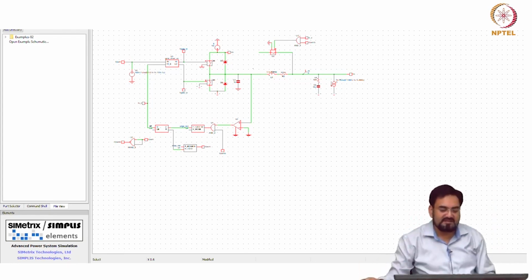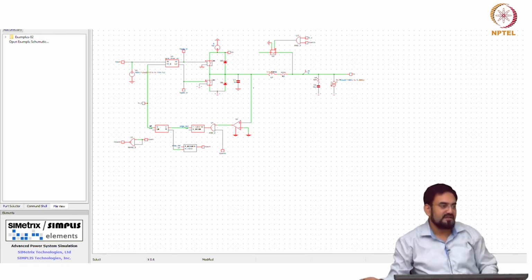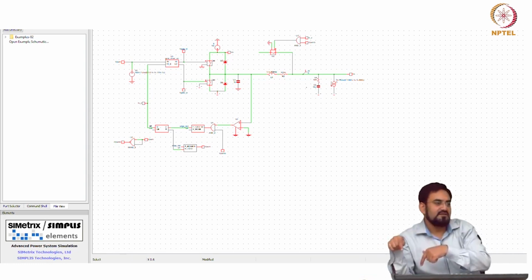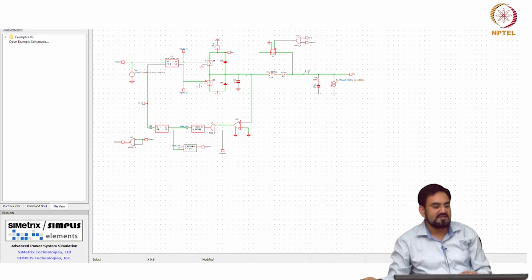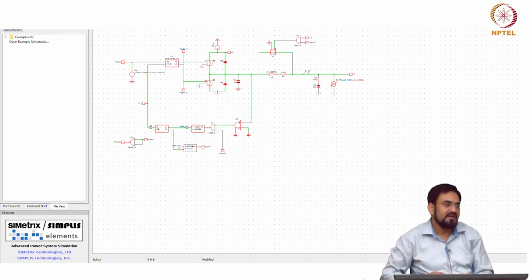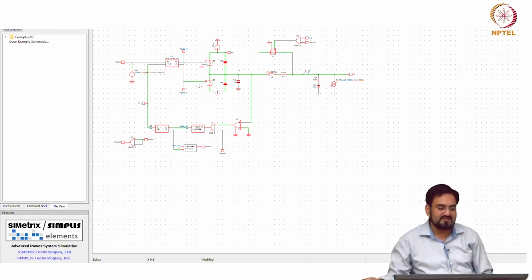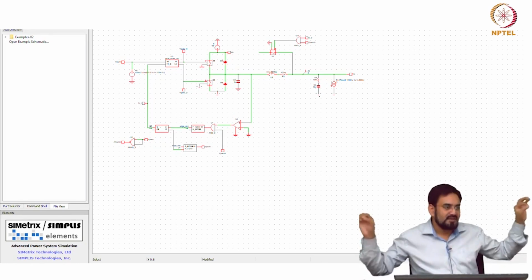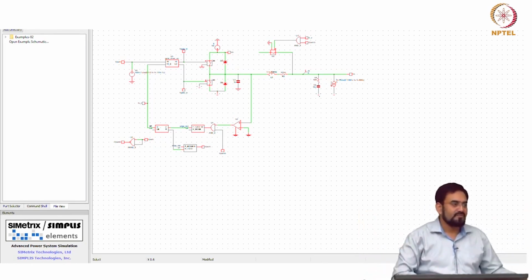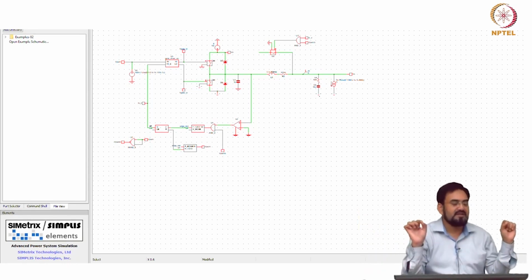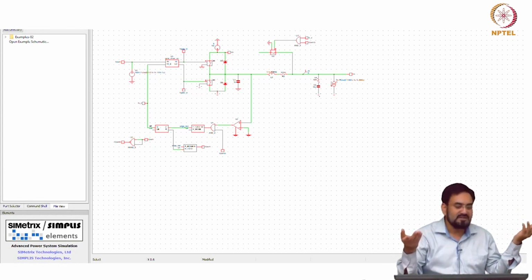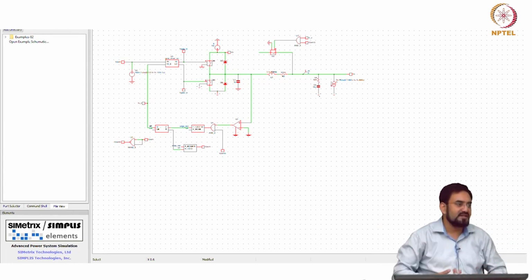So, when the current gets reversed, this voltage, and it is a high Z node, will try to charge very high. Okay, when it charges, the inductor current will go forward, and then it will try to discharge this node, then again the current will try to get reversed. Okay, so that's what happens actually. Charging and discharging of this node will keep happening until your whole energy is dissipated and the voltage across the inductor goes to 0. So, when the voltage across the inductor goes to 0, the energy will be 0 and it will not resonate. So, I can simply force the voltage across the inductor to 0.